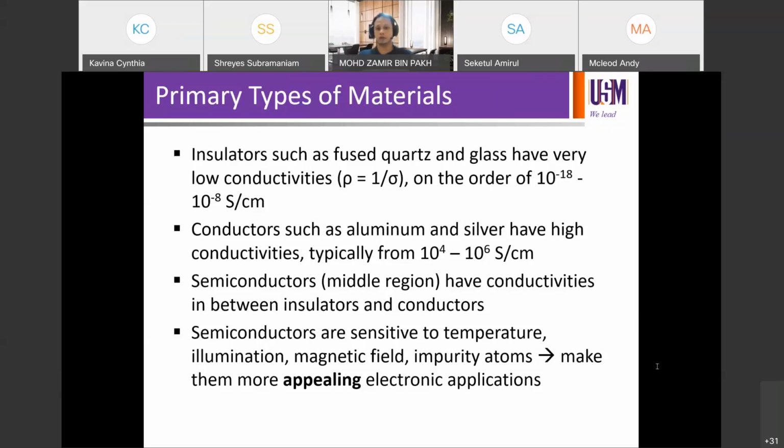So try to look into what sort of materials you are going to work on. Typically, if you talk about UV sensors, your materials should have a band gap above 2.5, 3 point something usually. If you talk about zinc oxide, it's somewhere around 3.3 eV, electron volts, right? So that it falls in the UV region and does the job perfectly, in comparison to other low band gap materials.